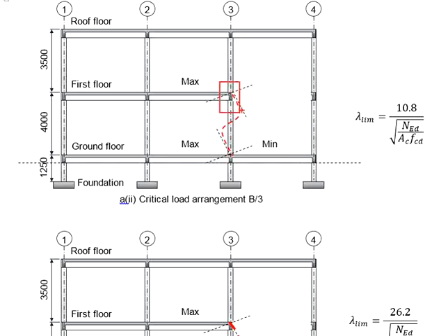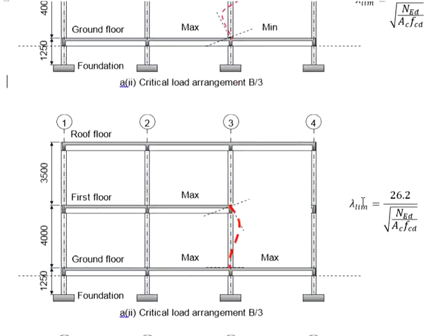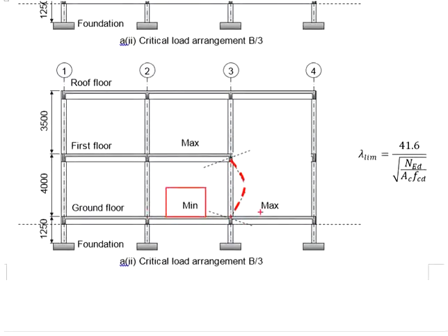For the upper end, the largest moment acting onto the column end here will be the maximum, since you don't have any beams here. As for the lower end, you can have either maximum here and minimum here, or minimum here and maximum here.